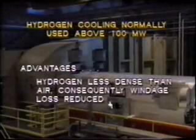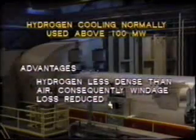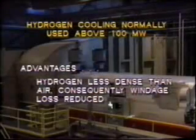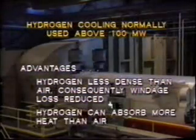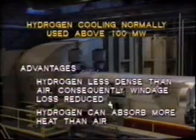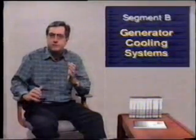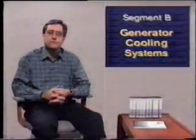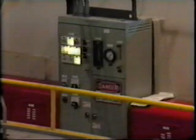Hydrogen is less dense than air, and consequently the windage loss, that is, friction loss due to rotation of the rotor, is considerably reduced. Hydrogen has a much greater capacity to absorb heat than air, therefore it is a better cooling medium. These two advantages mean that the generator can be made smaller than an equivalent air-cooled generator of the same capacity. Therefore, on the larger size generators, it is more economical to install a hydrogen-cooled system, even though this entails a much more complicated cooling system.